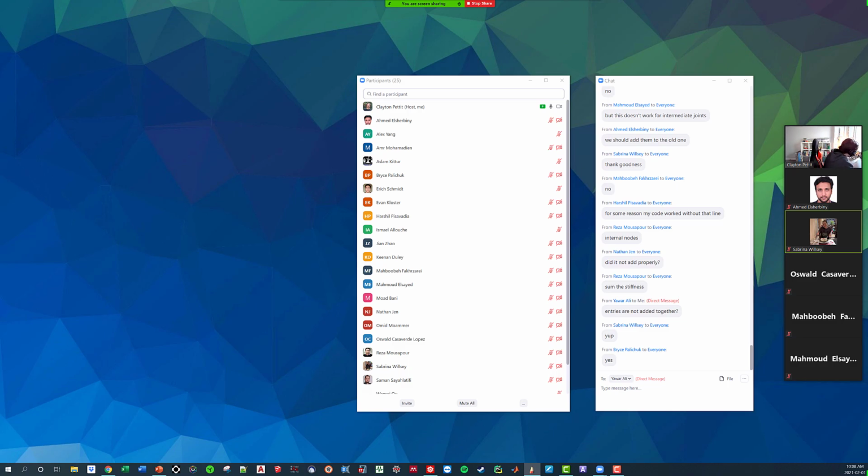So if we were to look at the degrees of freedom for this one, and I'll switch to, let's say, light blue, we know that this goes from node 2 to node 3. So this is going to be 2, 3, 2, 3. Therefore, if I were to look at this entry right here, we know that this is going to go into 2. So this is going to go right here.